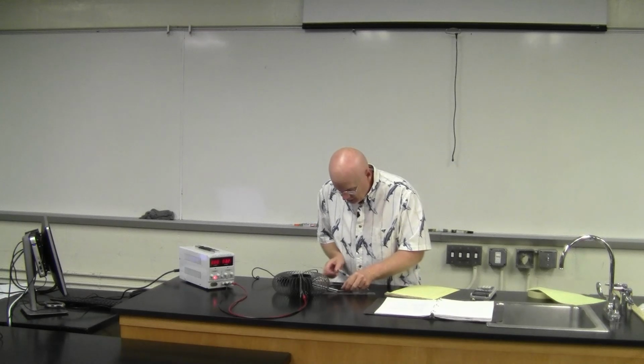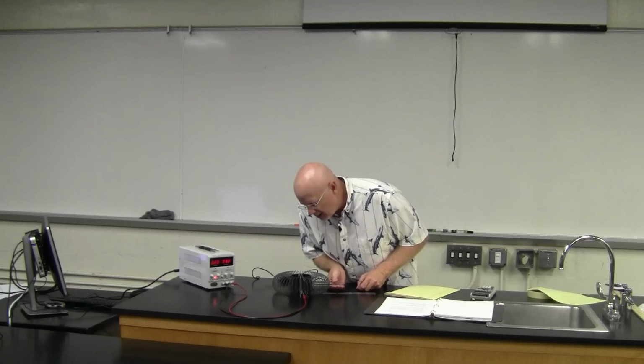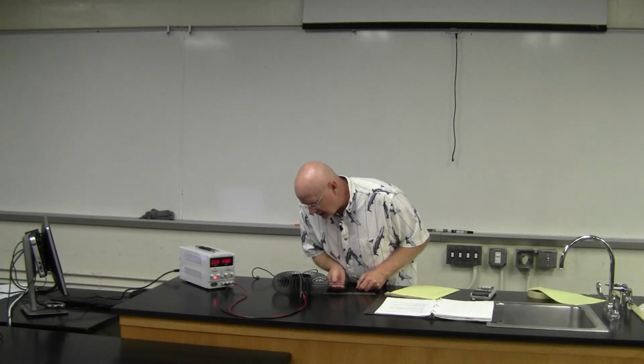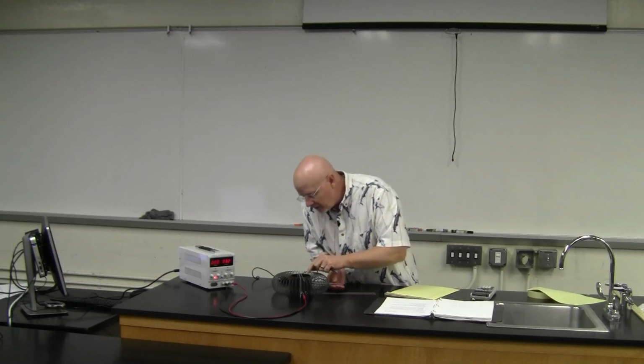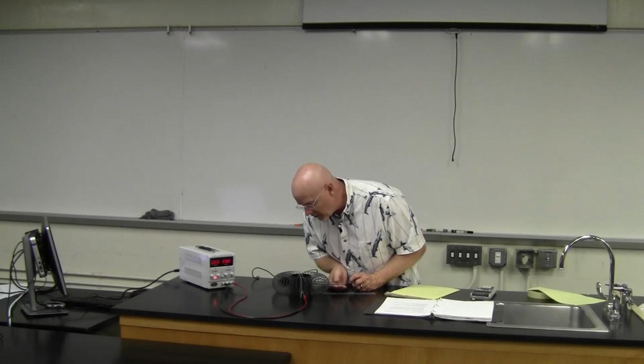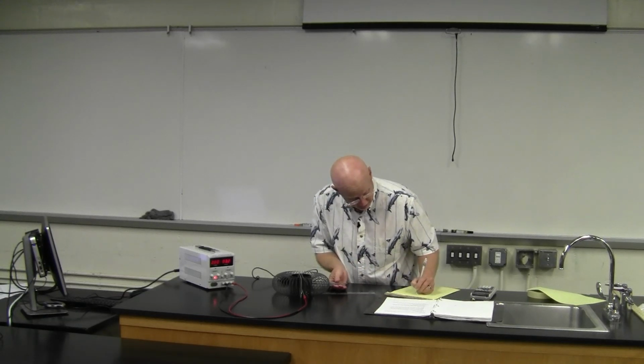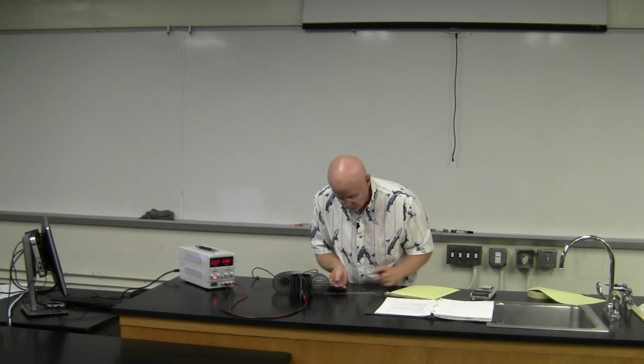All right, I'm going to adjust this, look over the top. Looks like I've got the right angle. Whoops, don't want to push it too hard. Looks like I'm at 1 centimeter. I'll look at my field probe, and it says 0.02. Move it back 1 centimeter till I'm over the 2 centimeter on the ruler, and it says 0.024.